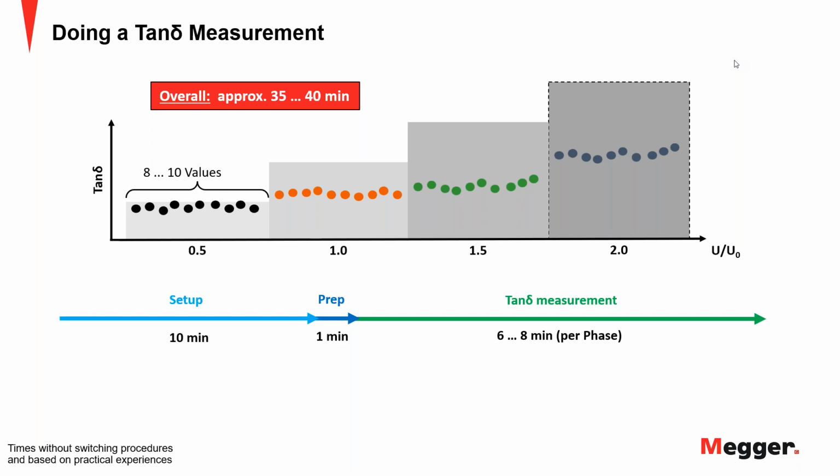What is the difference between commissioning and testing of service-aged cable? Well, I think Robert pointed that out in the beginning. He said we have two groups of tests: either commissioning tests on brand new cables, or service-aged cables where we do condition assessment tests. The difference is that the new cable obviously has no aging, so there are no aging effects. So any defects we can measure on a new cable are due to either manufacturing defects or workmanship defects.